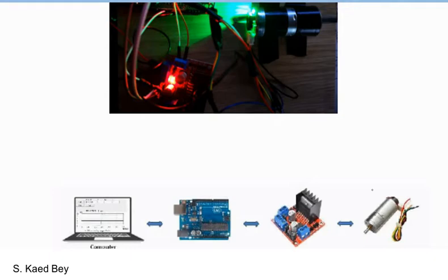In this video, we need to find the experimental PID solution to control the speed of the motor within the specific user requirements mentioned. To do this, we need to use the Arduino Uno and an H-bridge, the L298, and a 6-volt motor in this case, with a maximum angular speed of around 300 RPM.